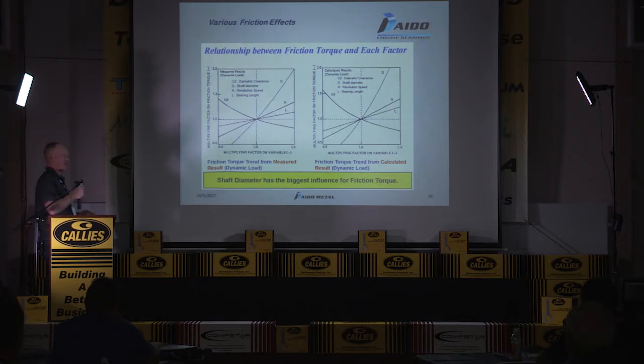So you have a lot of things to consider when choosing a target oil clearance, and whether you go with a smaller clearance or a larger clearance, whatever you choose, there's going to be obviously a pro and a con. There's going to be good factors and bad. So it's all about finding that balance that's going to be best for that engine and best for the longevity of the engine.